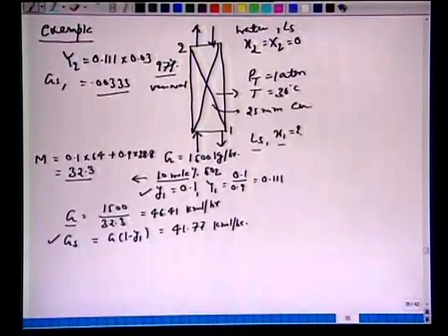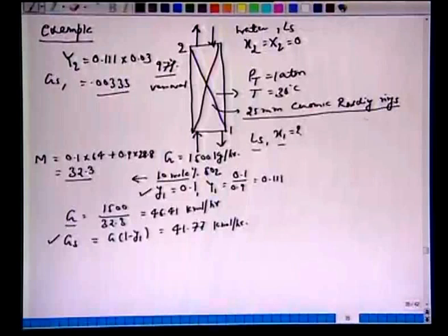of ceramic Raschig rings. Okay. So, as soon as we see this 25 millimeter ceramic Raschig rings, we can go to that table and we can get the different information we wanted for this packing factor which we require to do this hydrodynamic calculations. This is also given to us that mass transfer coefficient Kxa is 1.25